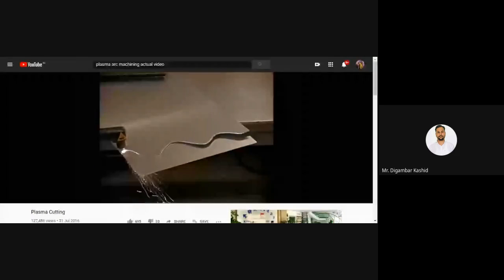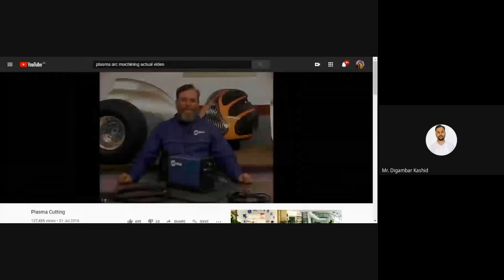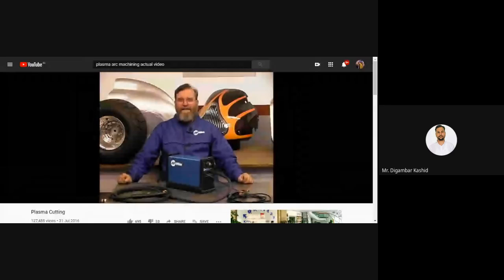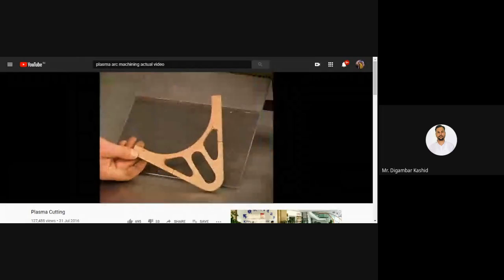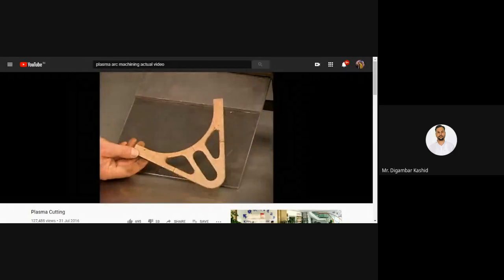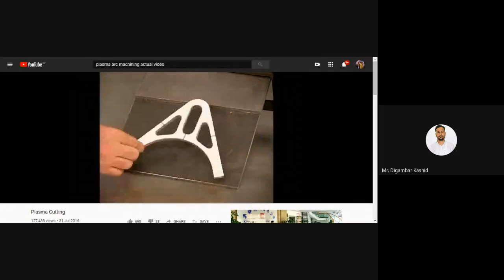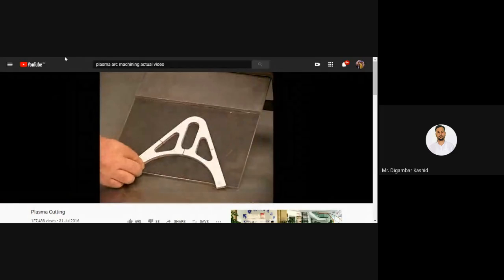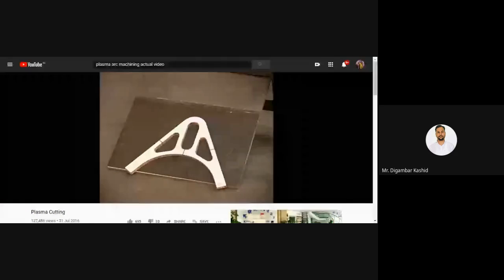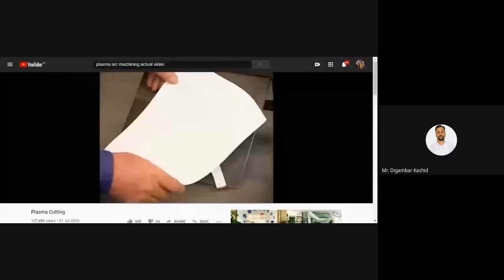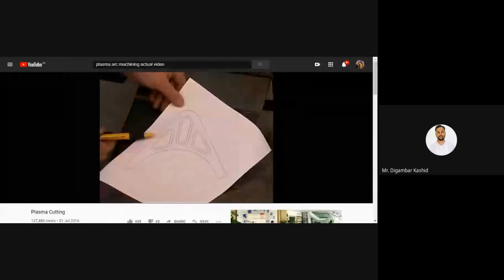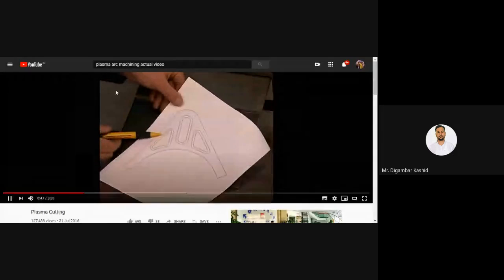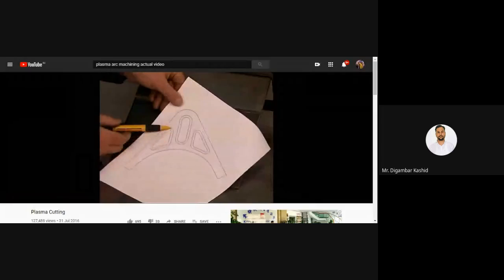For repeated cutting of complex shapes, you can make a simple guide from a non-flammable material. So here's a pattern used for plasma cutting that I've cut out of hardboard. These can only be used for occasional cutting, but for a few parts it works quite well. The way this pattern was made was actually from a drawing, and I prepared this drawing in a special way because the opening for the window in the pattern is larger than the finished cut will get.